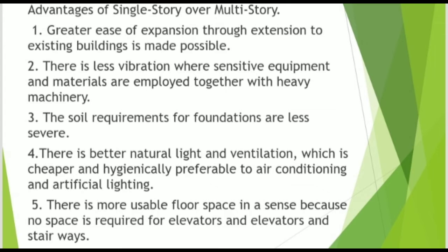Advantages of single-story over multi-story. 1. Greater ease of expansion through extension to existing buildings is made possible. 2. There is less vibration where sensitive equipment and materials are employed together with heavy machinery. 3. The soil requirements for foundations are less severe. 4. There is better natural light and ventilation, which is cheaper and hygienically preferable to air conditioning and artificial lighting.